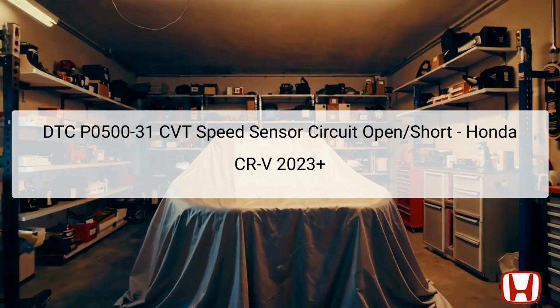The Diagnostic Trouble Code DTC P0500-31 indicates an issue with the continuously variable transmission CVT speed sensor circuit that either presents an open or short condition. This problem arises when the transmission control module, TCM, is unable to detect the proper signal coming from the CVT speed sensor while the secondary driven gear is in rotation.